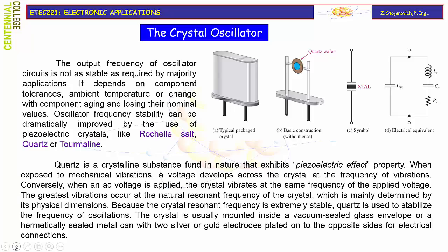Quartz is a crystalline substance found in nature that exhibits the piezoelectric effect property. When exposed to mechanical vibrations, a voltage develops across the crystal at the frequency of mechanical vibrations. Conversely, when an AC voltage is applied, the crystal vibrates at the same frequency as the applied voltage.